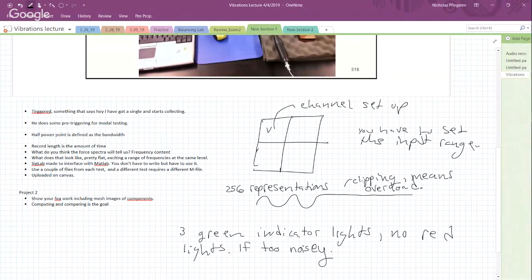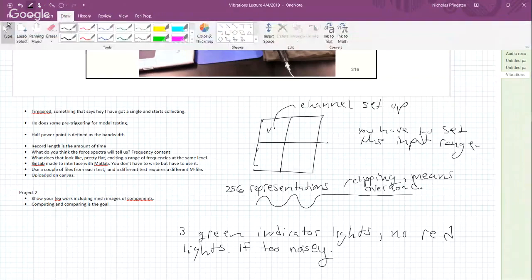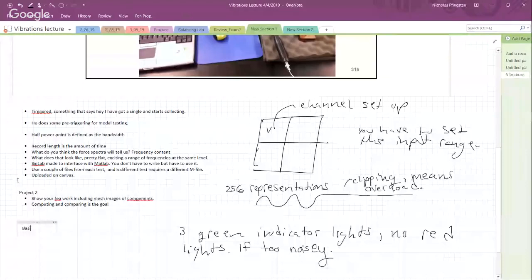That is one of the input settings, a special input setting that allows piezoelectric sensors like the accelerometer and hammer that we're using to be directly connected with one cable. So we basically go straight from these sensors into the analyzer. The analyzer, with bias on my input setting, is providing a low-level voltage that's powering the built-in electronics in both of those. Why do we have built-in electronics in this sensor?